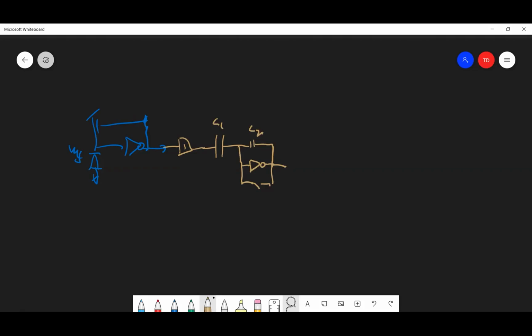So if I connect that switch together, this reset switch, what happens to this inverter? If I just short that switch, then it comes to a state where the output voltage equals the input voltage, right? So it's going to be some balance voltage where the two voltages are the same. At that point, it won't change its voltage, right? It'll come to some equal balance voltage. So that'll be like connected.